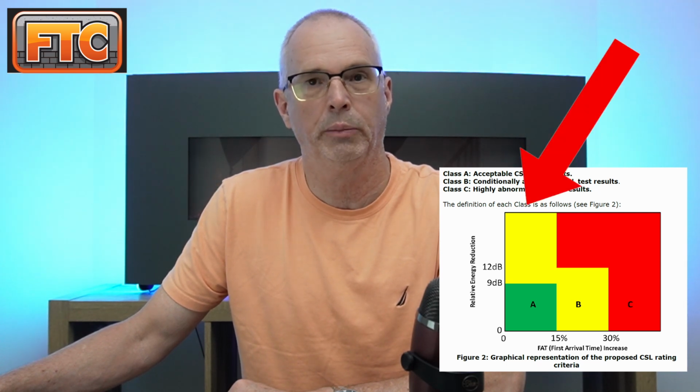The end result of the evaluation criteria by DFI ends up in a table like this. You can see per this table you have a concern about drilled shaft concrete quality based solely on a reduction in signal energy, which simply does not make sense. In fact, nowhere in the DFI guidance is there any differentiation between a true drilled shaft concrete quality issue and mere data issues that are in no way related to variations in concrete quality.